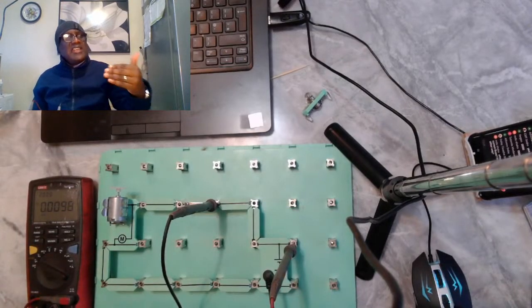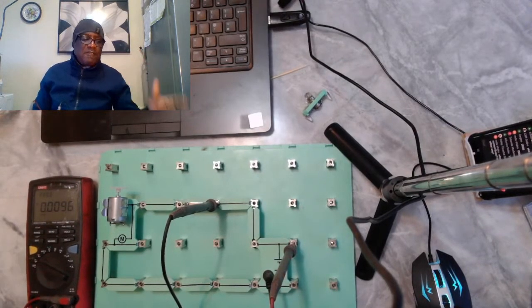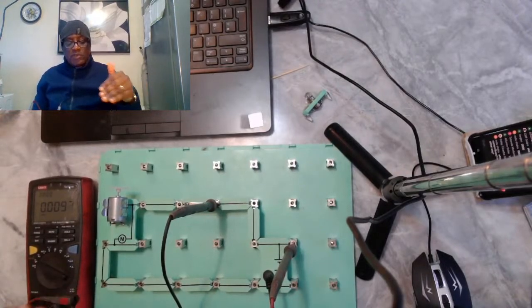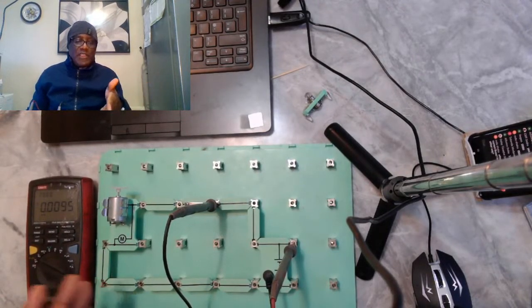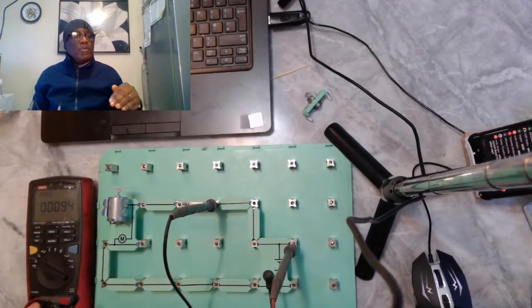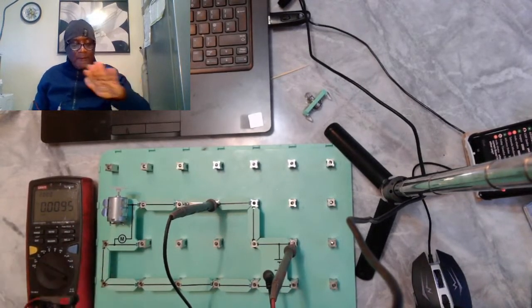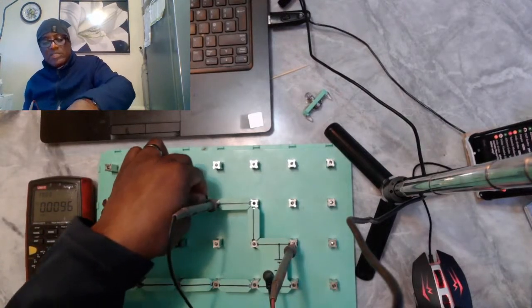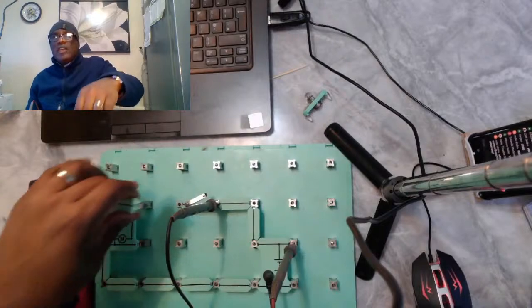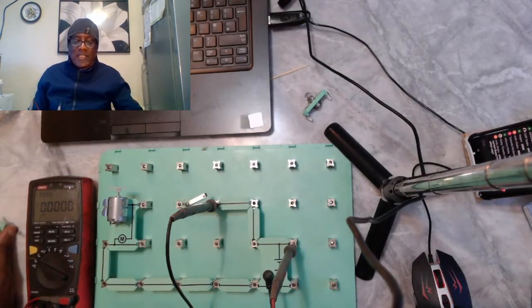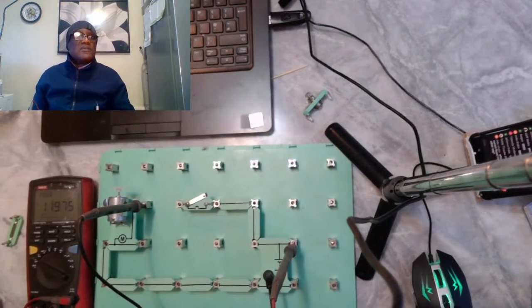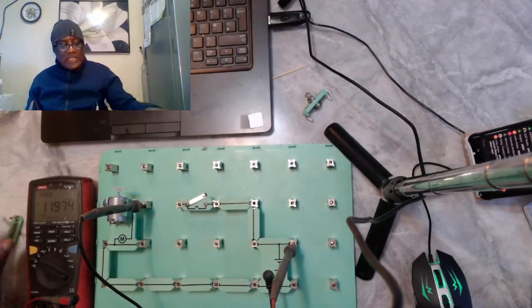On the positive side, usually it is 0.5, or on the ground side 0.25 or 0.3. It's still acceptable. But once you start to get a volt, then you know that you've got high resistance somewhere. You might need to check your connections. But anyway, that's not what we were talking about. What I wanted to establish here today was that when you have an open in a circuit, it will be on the side where you find voltage. So that is established.